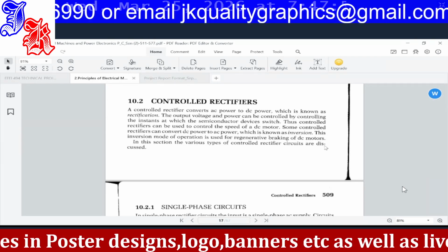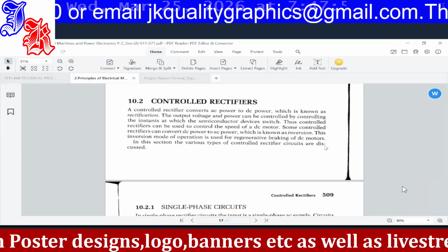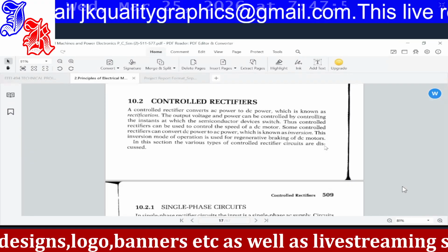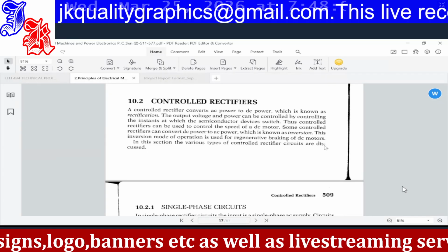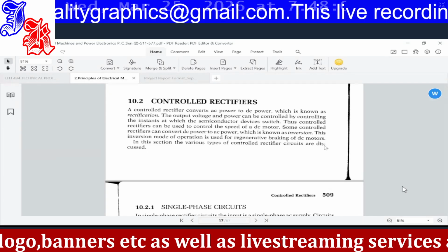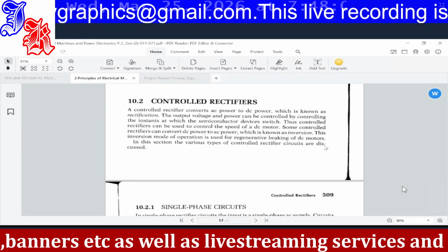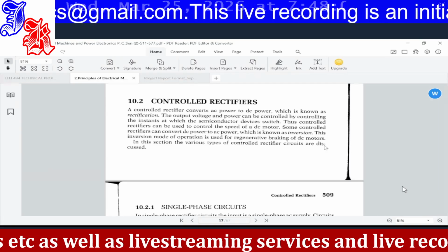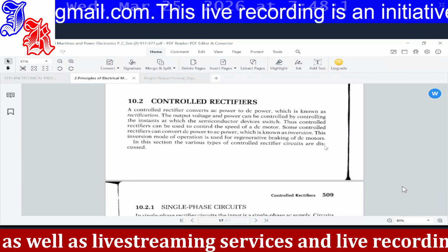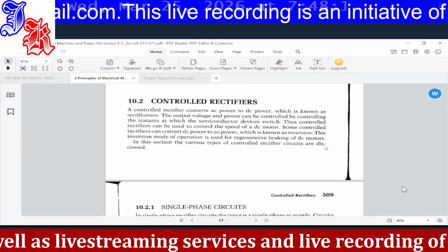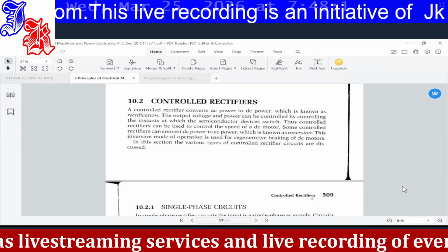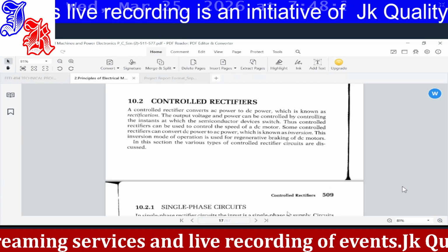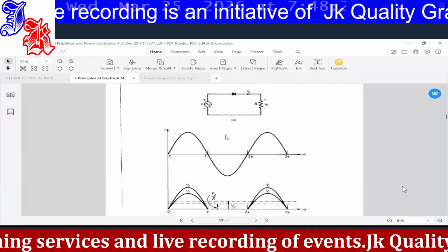But for diodes, the moment we bring the P and N material together and connect them in forward bias, it just starts conducting. But for the thyristor, we still have to add the gate current, and we can choose at what time within the wave we want it to ignite, or at what point.